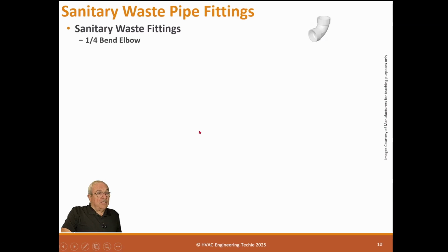Sanitary waste fittings. Okay, we've got quarter bends. This is the waste, so you can see these are longer bends than normal. We have eighth bends, so if you need to go 45 degrees, you can do that. Sanitary tees. Now, I'm going to show you just the basic fittings.